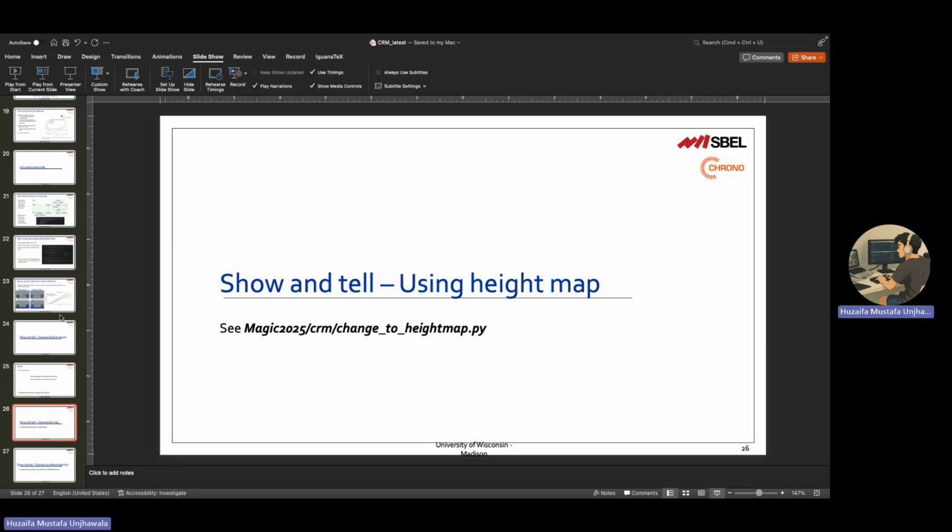Yes, for sure. I think the actual results where we got some physically meaningful results used half the spacing that we're currently using and more depth. So we got a lot of particles in the soil on the surface as well as a lot of particles on the tire to resolve the friction. I have noticed that this plays a very important role in getting physically meaningful results. This is one of the things that I run a lot of simulations on to get the right initial spacing and the kernel radius. So it's about stability and accuracy and also speed. It's a tricky thing to balance.